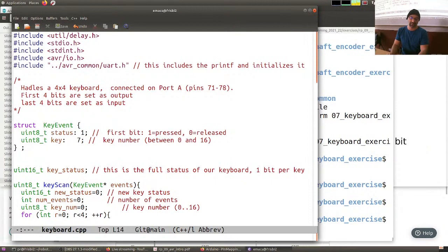What you see here is a synopsis of the bit fields in C. I'm just giving you insights. If after a variable you write a colon and a number, this means that you are selecting that number of bits of whatever follows. So this means: give me a bunch of bytes in memory, and the first bit of this bunch of bytes, make it accessible to me as a thing that I call status. It lets me access it as if it was an integer of 8 bits, but of course, you will only be considering the last bit.